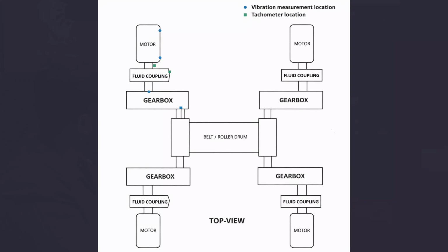Okay, can you give a quick briefing on what it was all about? Of the subject itself, this process industry, in particular the steel industry that I'm referring to, uses large conveyor belts to transport the ore and the fuel material to the furnace. These have very large motors, like 4 of them together, driving the single belt. 3 of them will be in operation, 1 on standby. And because of this large load, there is varying load, which means the torque and the load conditions are all the time changing.